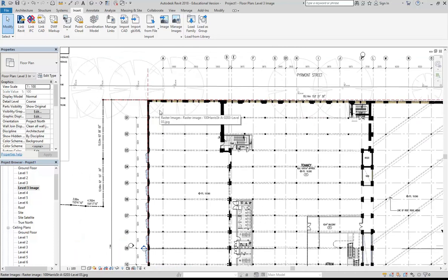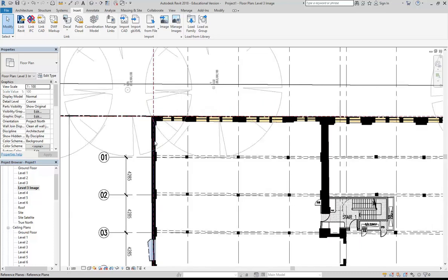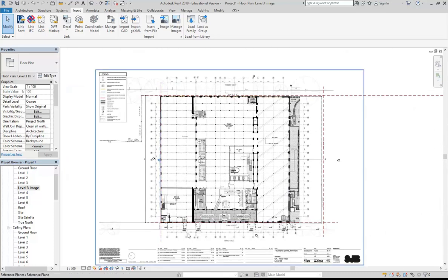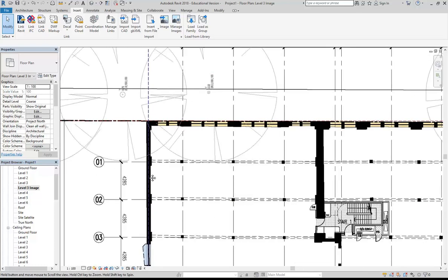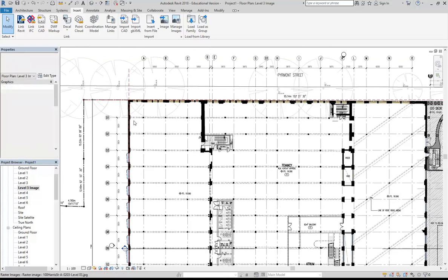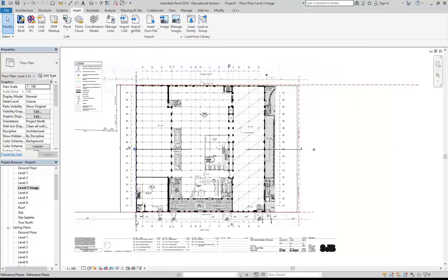So Revit doesn't like angles, especially angles that are slightly off orthogonal. You can still do them, and you have to here, because that's a pretty decent angle. Even though I said it's small, it's big enough to worry about. You can see there it slopes away slightly. So you need to put that in, and there's a bit of a trick.